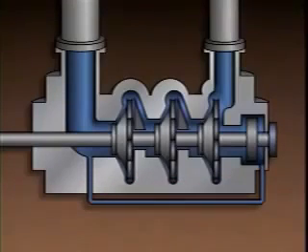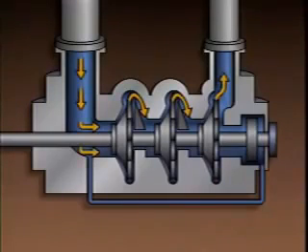Each stage of the pump has its own impeller and volute. In the volute, the liquid's pressure increases. Each of the first 2 volutes discharges into the suction eye of the stage that follows it. The 3rd stage volute discharges into the pump's outlet. So in this pump, the liquid flow path is from one end to the other.